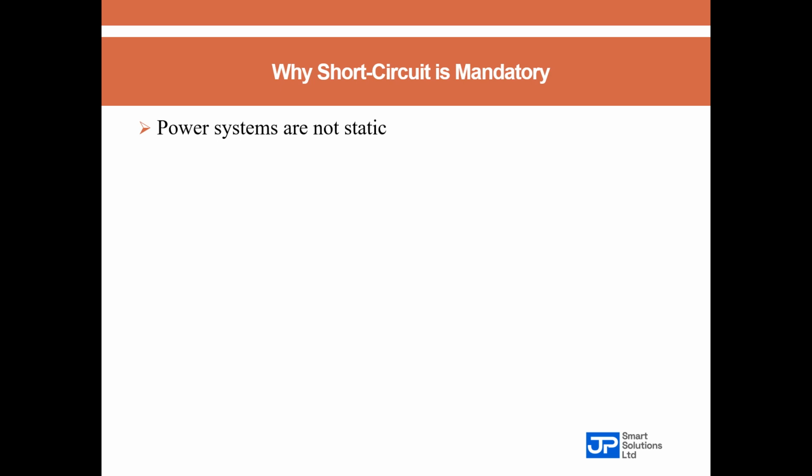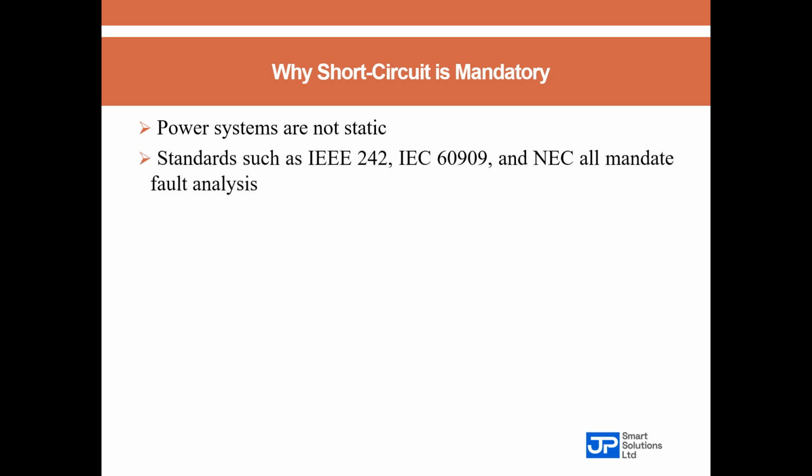The moment you change one transformer, or you add a motor, or you increase the utility capacity, your fault levels change instantly. Now, this is why standards such as the IEEE 242, the IEC 60909, and the NEC all mandate fault analysis. It's not a suggestion, it is a requirement.